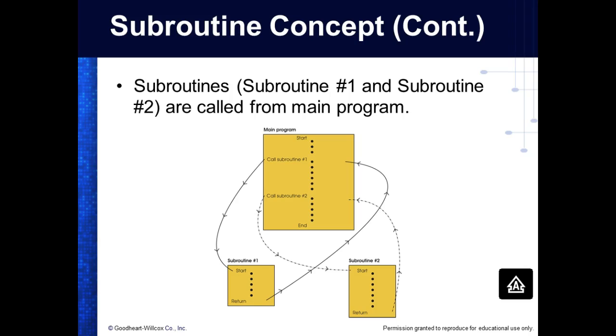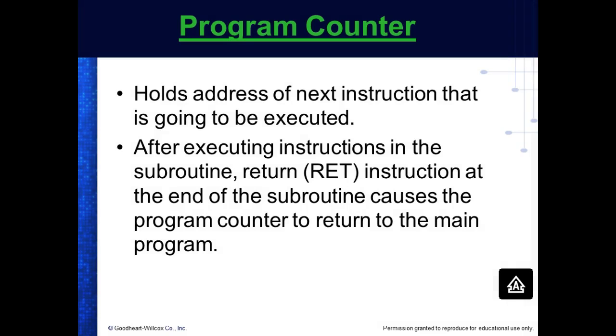So it goes to the next rung. We don't do the JSR again. So we have something called a stack that holds the address of the next instruction to execute. So when they say next instruction, here we're talking about the next rung, right?